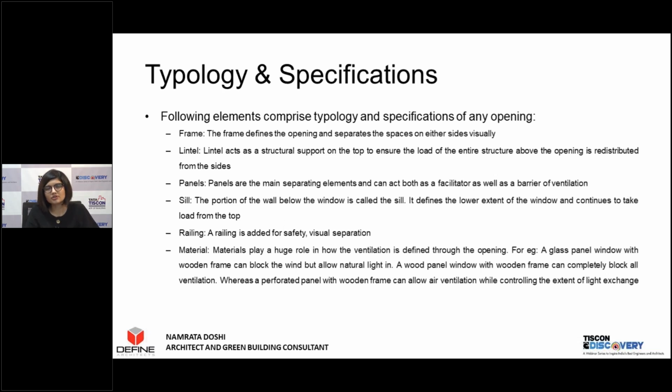It will define the size, the location, and how it looks. It is typically the box, if not a box then any other shape, in which your opening is placed. Lintel is what goes above your opening. Typically for doors, lintels act as a structural support. So imagine you have a large wall and you're suddenly puncturing it. You're actually disturbing its load distribution.